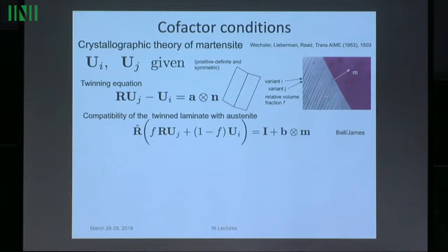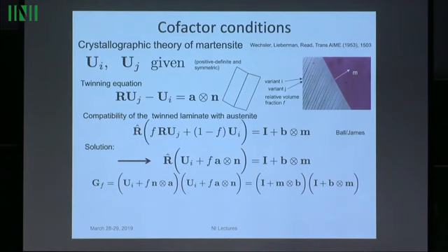We have 2 solutions of it. So we suppose we've done that, and then let's focus on this one. How would you satisfy this? If this has already been satisfied, that means the R is now known. The unknowns here are the volume fraction F, that's the volume fraction of one set of bands versus the other, the red bands versus the blue or green bands. This is a rotation matrix, and these two vectors B and M. In Peter's notation, B tensor M would just be written BM.